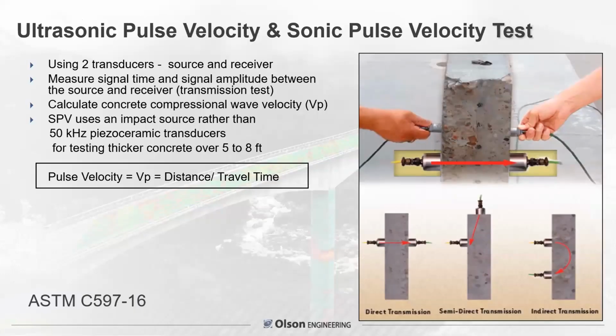So we then did ultrasonic pulse velocity. The nominally 50 kilohertz transducers are shown there. They're grease coupled, typically with a light lithium grease. You can use an ultrasonic industrial or medical gel if you're worried about staining the concrete, which you should be. People don't usually like really black grease on their concrete. The lithium is relatively white. But you push on each side and you send. One is a sender, a source, and the other one is a receiver.